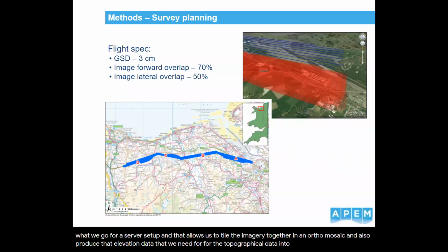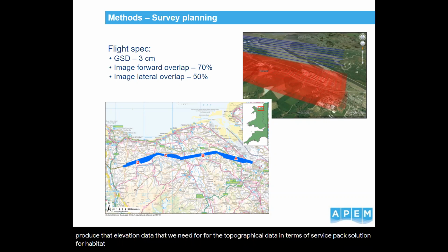In terms of survey spec, of resolution, for habitats, we often go at 3 centimetre resolution. It can go a bit higher than that from airborne data. It can go to 2 centimetres, or for some of the lower detail requirements, when wetted widths are the main focus, then you could go to a lower resolution than that. That could be 10 centimetres, for example.